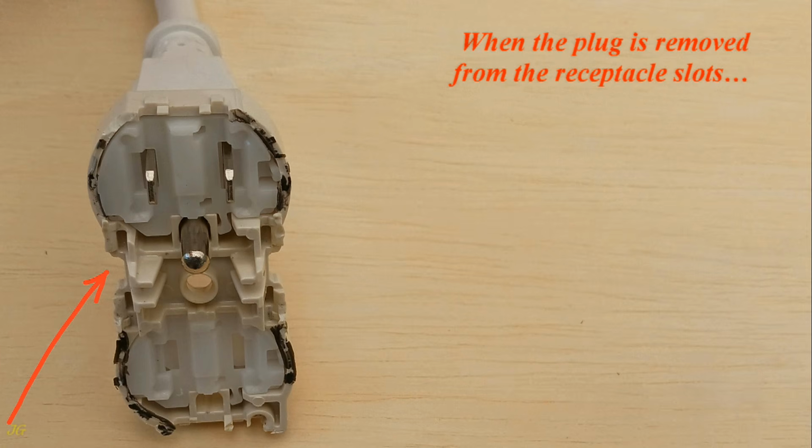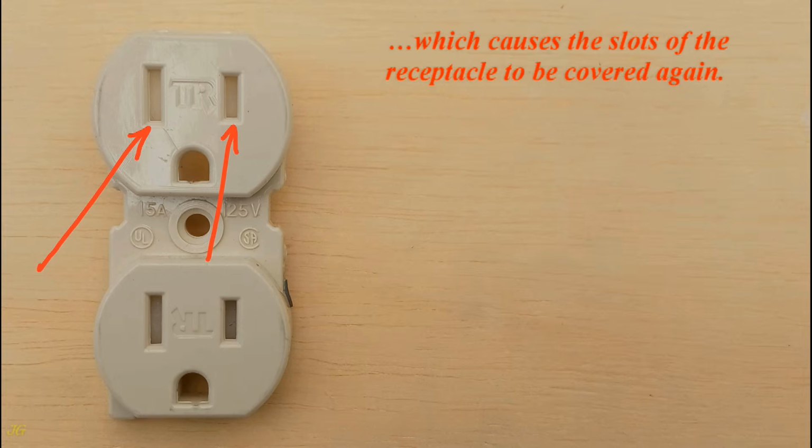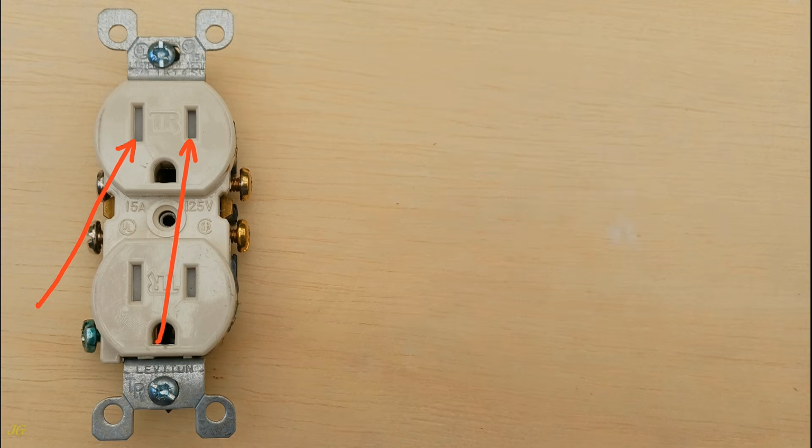When the plug is removed from the receptacle slots, the spring that constantly presses the shutter moves it back to its previous position, which causes the slots of the receptacle to be covered again. Uneven and non-simultaneous hard pressure on the slots of the receptacle will unbalance the shutter mechanism, preventing the plug from being inserted and consequently damaging the receptacle tamper-resistant mechanism.